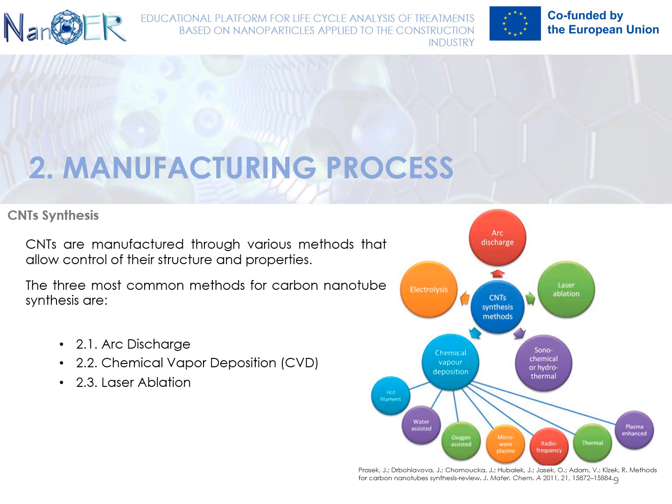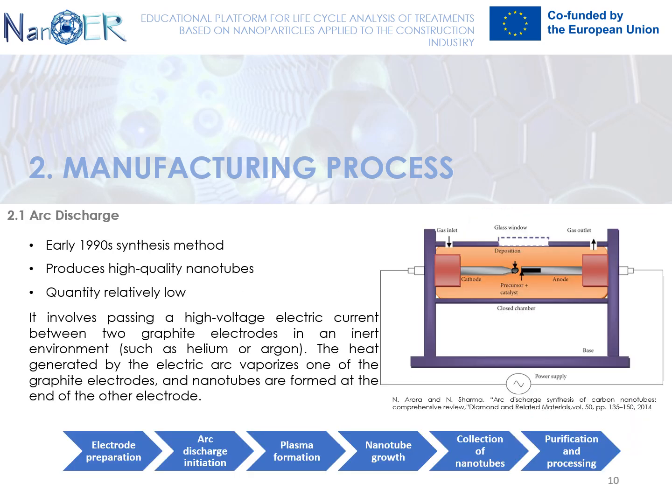CNTs are usually manufactured by 3 processes. These processes are electric arc discharge, laser ablation, and chemical vapor deposition. Each of these processes produces different types of nanotubes. Arc discharge is the oldest way of producing carbon nanotubes. The high temperature which goes along with the experiment evaporates carbon atoms. To be more specific, the electric arc vaporizes a graphite anode mixed with transition metals, ferrum, cobalt, or nickel, combined with a graphite powder.